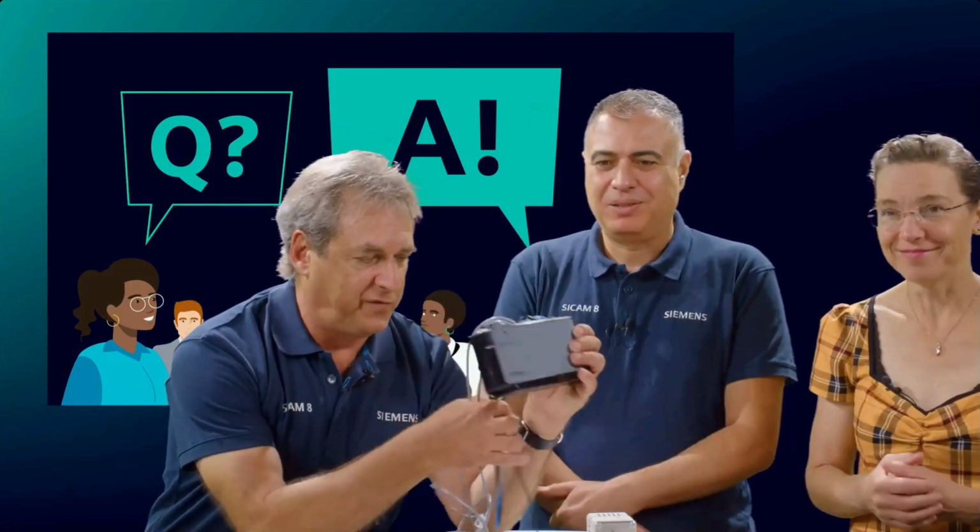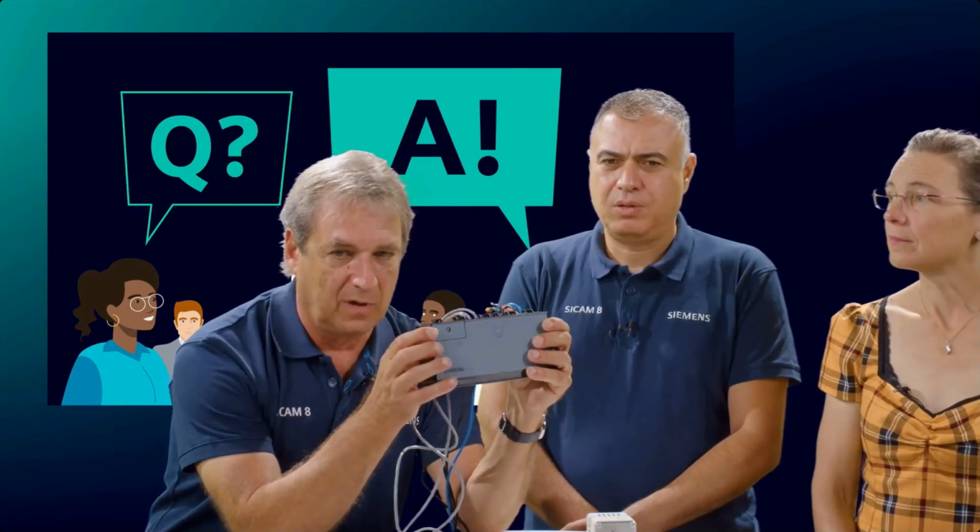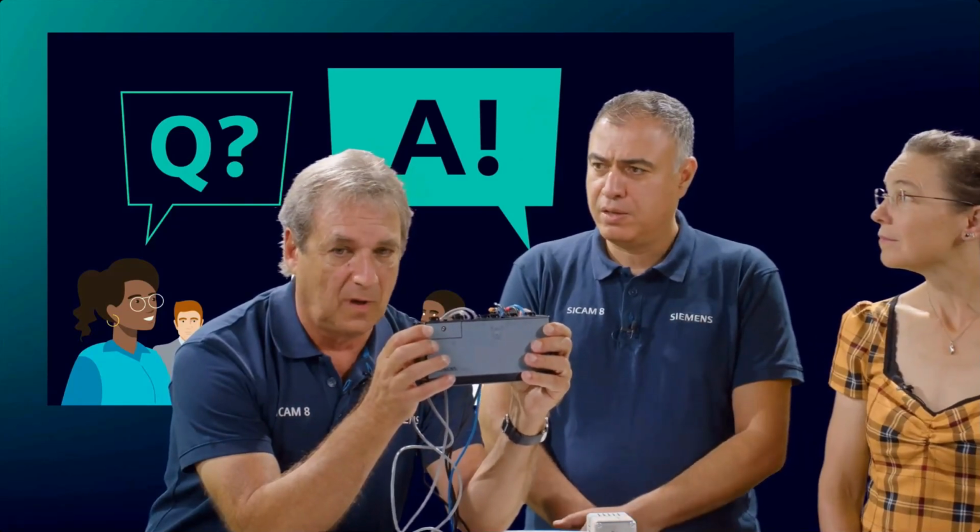As mentioned before, if you do not want to use the disadvantages with the low voltage, then via these two interfaces, you could connect medium voltage devices. Short circuit indicators, for example, so we can receive the voltages and currents from the medium voltage via the connection. Exactly. So use it for low voltage insights and add some information from medium voltage. That's typical for RMUs, for instance. That's a typical use case.